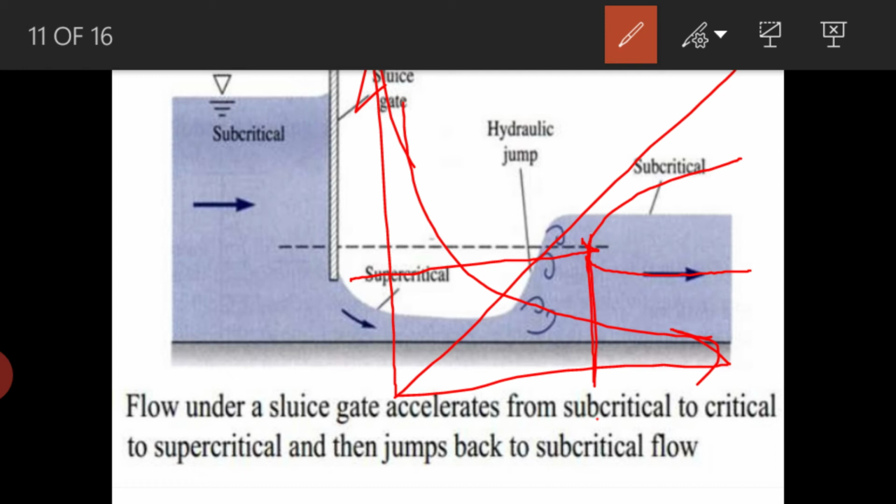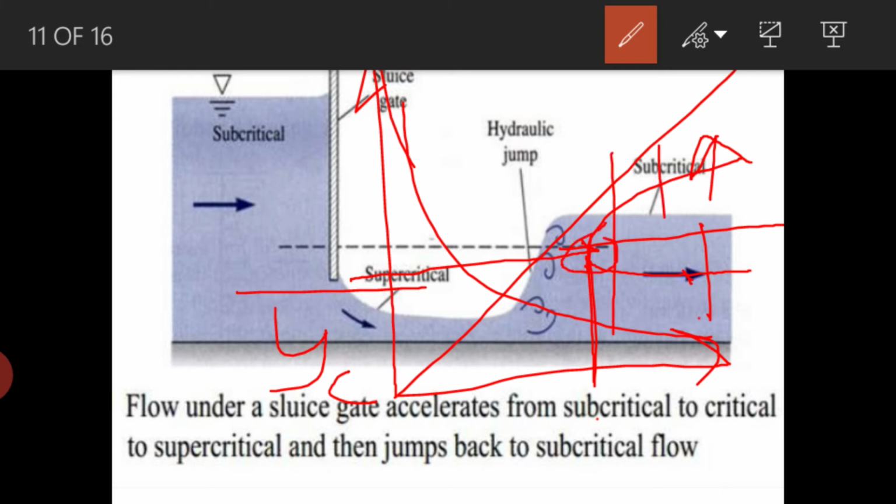Corresponding to the minimum energy, the depth we were getting is the critical depth, and above the critical depth, that is the subcritical flow condition, and below critical, that is the supercritical condition. Leaving this particular point, wherever you take the depths at a constant discharge, you will get two alternate depths, and we have solved some problems on this in the previous module.